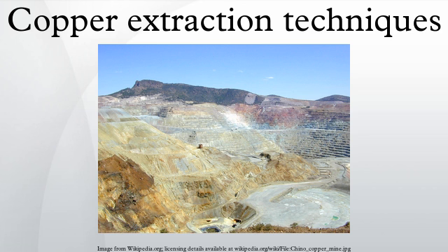The reverberatory furnace acts to allow these species to approach chemical equilibrium at the furnace operating temperature. In this equilibration process, oxygen associated with copper compounds exchanges with sulfur associated with iron compounds, increasing the iron oxide content of the furnace, and the iron oxides interact with silica and other oxide materials to form the slag. The main equilibration reaction is Cu2O + Fe(S) = Cu2S + Fe(O).